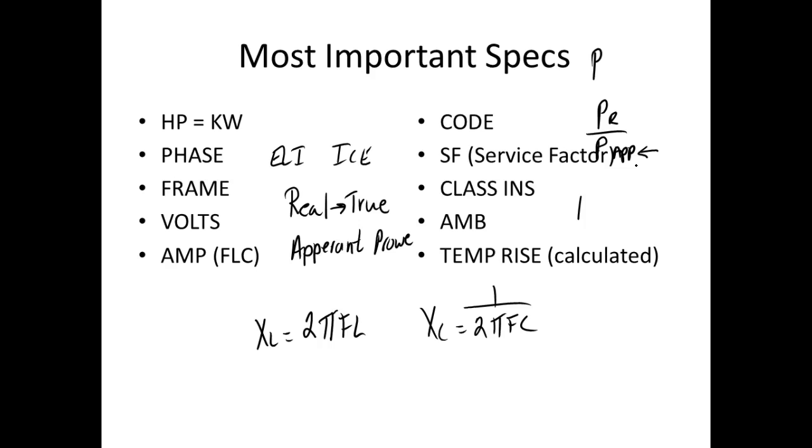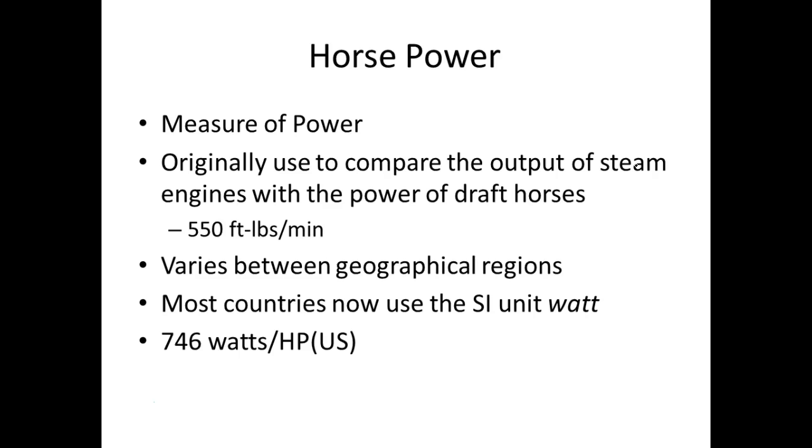So motors are predominantly inductive. So they try to create a lagging power factor. If they can give us some type of indication of what type of capacitor I can add in parallel with that thing, then we can get the power factor up to 100% or 1. Okay. So there's actually another measurement, and I think that's in this thing right here.